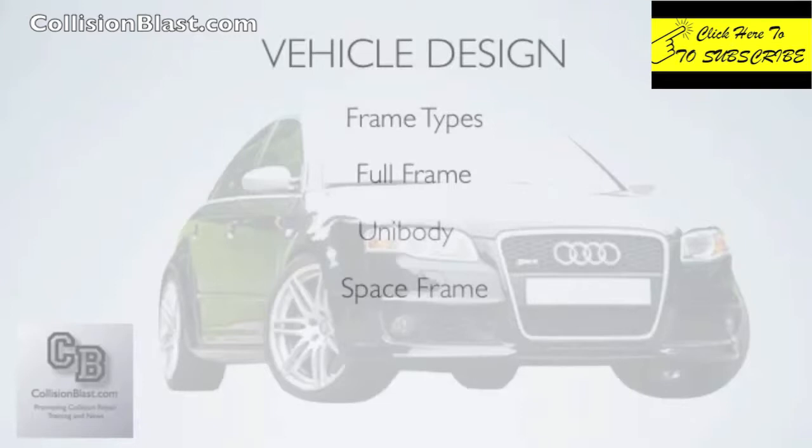If you think of a funny car or race car, the bodies on there are just for looks. There may be some aerodynamics, but it's mainly just for looks. You could take the body off and that car would still be just as strong, the tube frame. Well, that's kind of what a space frame is. So a space frame is a type of unibody, but a unibody is not a space frame.